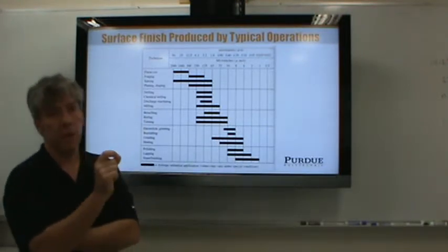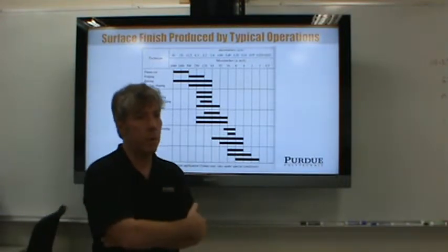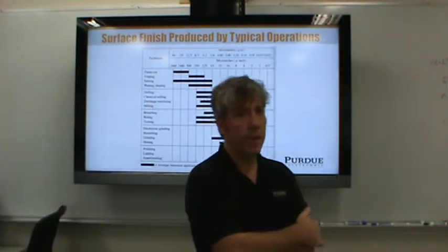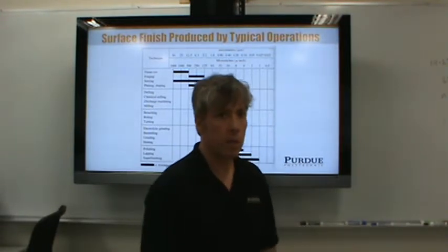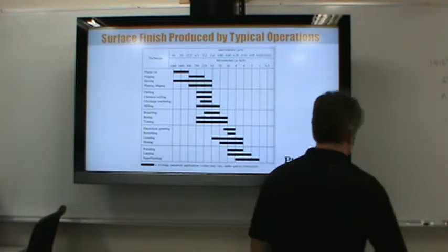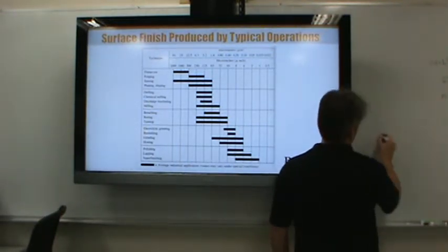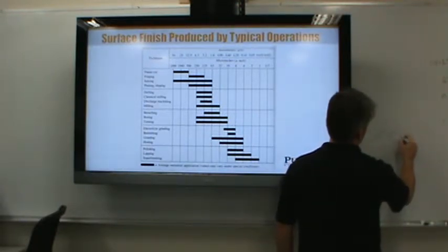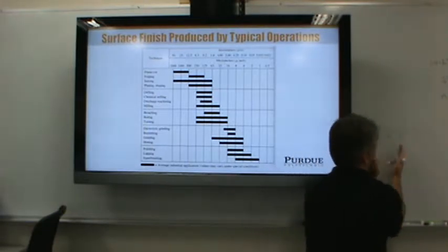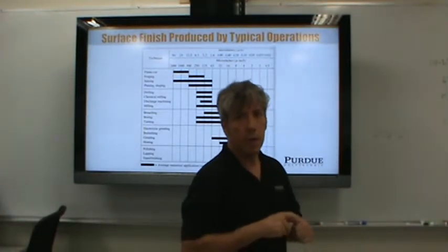But these were really small. These were only about a 32nd of an inch square. So the press needed was very small. We didn't have one, so I just designed one. Well, the tool needed to cause that crimping action is, here, let me draw it beside so it'll end up on the video. It's a pretty simple shape. You need something about like this. And what happens is it engages with the metal sides, rolls them over as you drive it all together, and it can crimp whatever you want. Okay, it crimps on the wire.